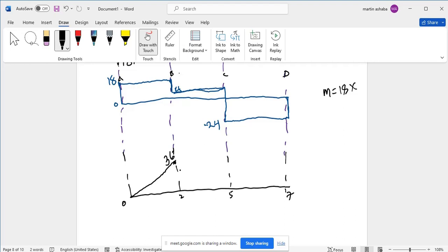It gives you 28 plus 8, which gives you 36, which means our bending moment starts from here, 36. Then we follow the equation of a line, which is 4x plus 28. Since I know this is the equation of a straight line, I just go to x equal to 5. At x equal to 5, 4 times 5 becomes 20, plus 28 becomes 48.